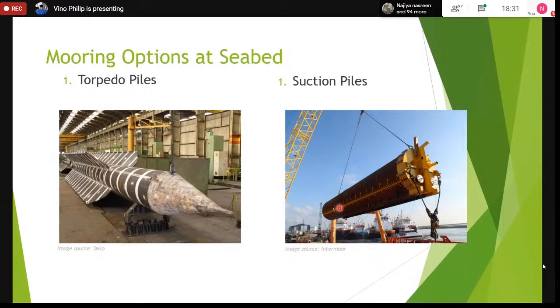And then after that, to make it penetrate further down, you will put vibration mechanisms and hammering mechanisms on it, and you will use suction to displace the water column. When it goes in, this whole area will be filled with water. So you have to displace the water column and pump the water out. Actually, it's not the soil that climbs up. It's more like a straw.